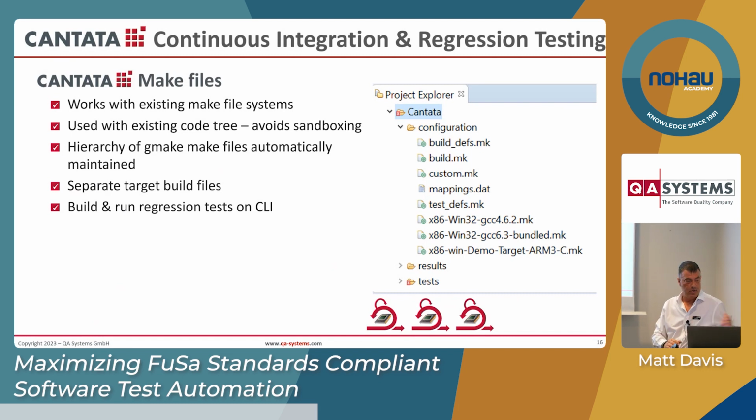So outside stimulus, like if there's a UART complaint, that becomes a little bit difficult in the host. Yes, it does, and that's why a lot of people will run tests on a target platform, even though it depends on the nature of the device, they don't have to run a test on the target. And again, where you run your test is often dictated by the safety integrity level. So if you are doing an ASIL D system, or the highest level of integrity, say for a Class C device in medical, you are expected to run your test on the physical hardware.